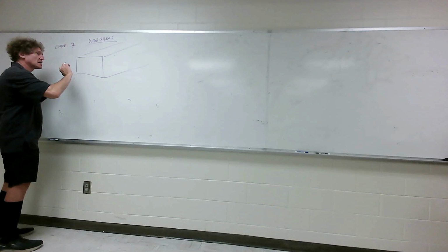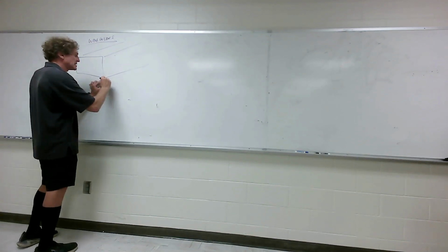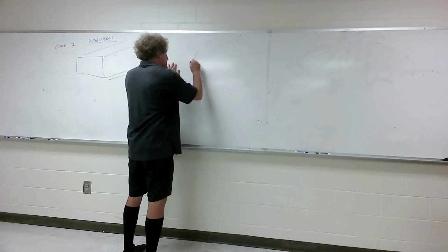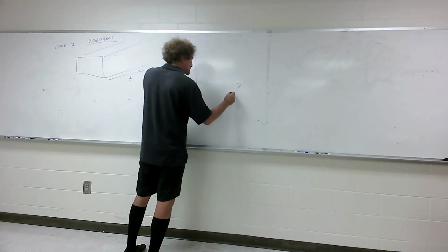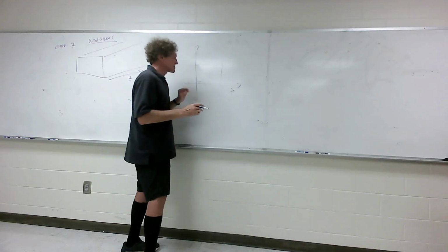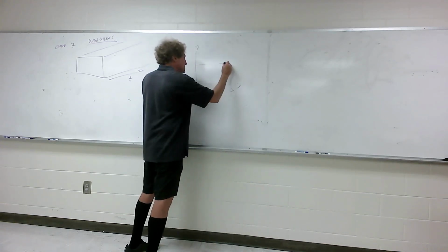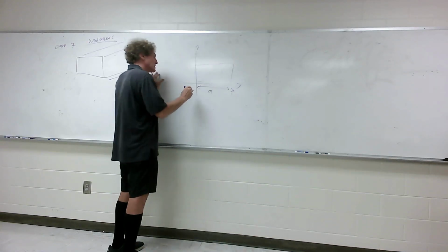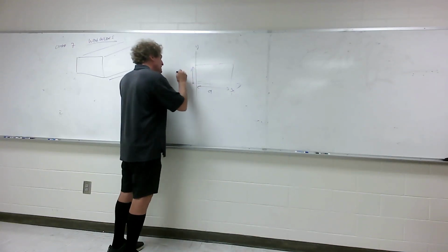I'm just going to blow this up. The cross section doesn't change. Usually this is the z direction. But if we look at this, and this is consistent with Wentworth's book, if this is x and this is y, a waveguide is a metal surface. Let me draw that a little bit. It'll have a horizontal dimension a, and a vertical dimension b.